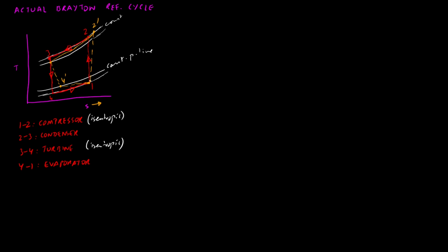And if we look at the compressor, the efficiency is going to come in now, because this is the ideal process, 1 to 2. 1 to 2 dash is the actual process. And so we usually write it in terms of efficiency, which is known as the isentropic efficiency. Subscript C is for the compressor, and isentropic represents the isentropic efficiency. It's going to be in terms of the actual by ideal work done, or in terms of the ideal work done, which is the isentropic work done.